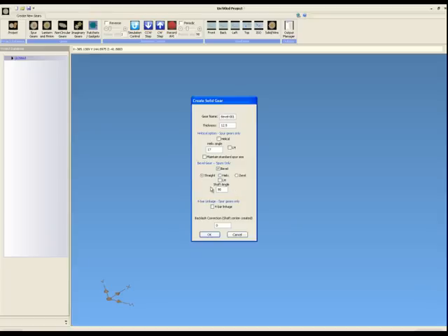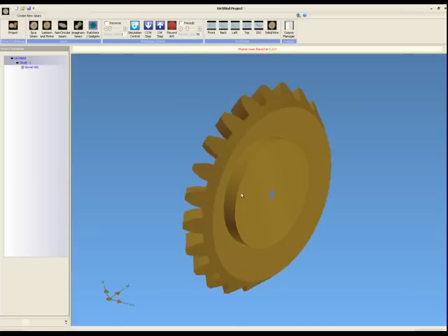If all this sounds like jabberdy nonsense to you, good, ignore it. It's really not that important to you. Suffice it to say that when you select a bevel gear, the system will compute the length of that gear to the apex of its cone. It will take 25% of the value and try to assign that to the thickness of the face width. If the thickness of the gear is set less, it will take the thickness of the gear that you've set. So in this case, we're asking for a bevel gear, straight, 90-degree shaft angle, with a 12.5 millimeter face width. Say select, and we'll end up with a master on the screen showing us that gear.